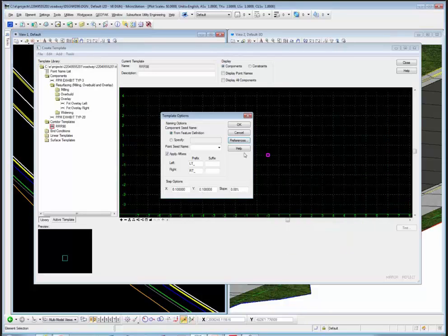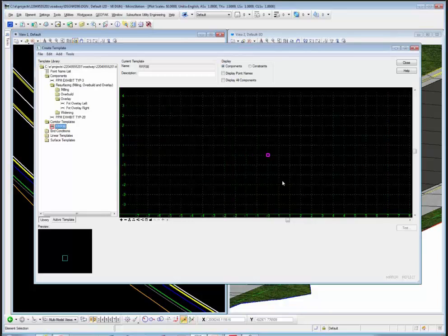It's also going to snap to the nearest tenth of a foot in the grid, so that you have a closer snap ratio. It's kind of like a grid lock. It's easier to snap to points if you have this on a 0.1 than if you have it at 0. You won't ever find anything. All right, so then it's very simple. All you have to do then is, I brought over all these resurfacing components.